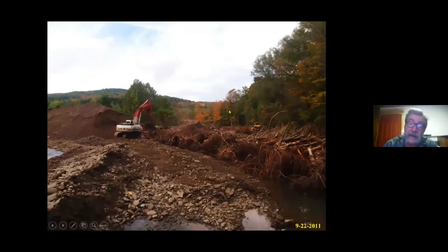So here's where it broke through to threaten that water supply. They've lined up all that woody debris that they had there, taking advantage of it in that channel that broke through. They're burying them below the grade of the water. And again, here's the stream way over to our left. They're burying that material below that stream elevation. They're putting some rock on top so that they don't become mobile when that water comes up again and starts to rip and tear. And they're going to bury all of them.